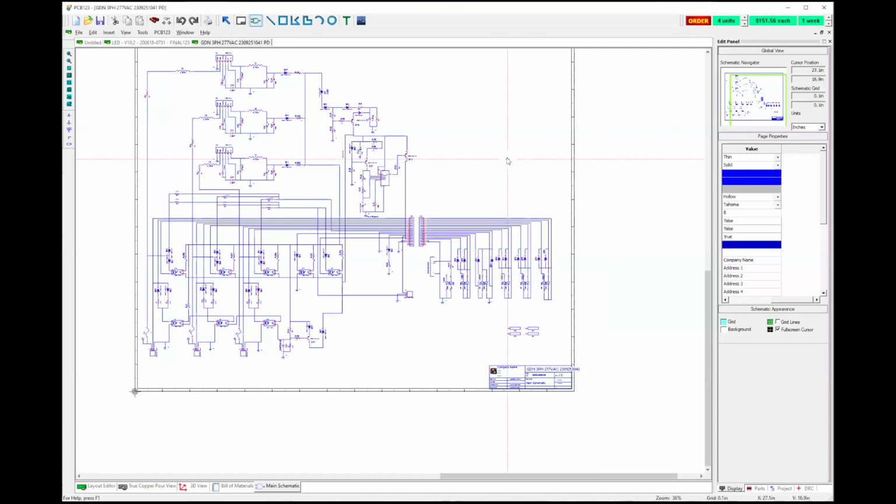If I use the manufacturer's part number to name the symbol and to name the footprint, and then add that information into the part number and such, then all I have to know about that part is that it is, for example, a TCMT1600. And anytime I want to place that part, I just enter that string into the search, and it pops up.